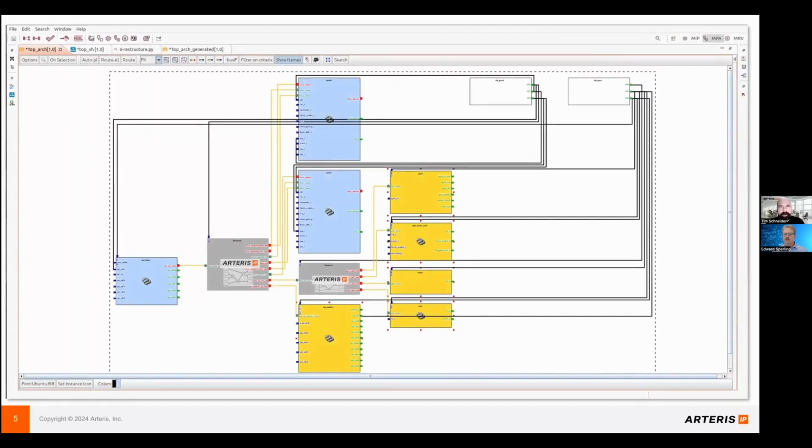So what I've got here is a very small subsystem, but this could be considered part of it, maybe a tiled operation. We've got customers with the whole ARM and RISC-V architecture where they've got a CPU to manage that, but it's a small tile with some peripherals that has to talk to another block. So what I have circled here are 4 or 5 instances, like subsystem peripherals, and I would like to collect these and put them in another level of hierarchy.